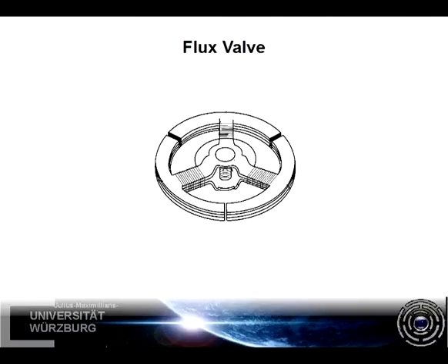The flux valve is essentially a compass that senses the magnetic field by exciting 3 coils using alternating current and measuring the resulting magnetic field. If there were no other field present, the resulting field would be cancelled out to 0, since the alternating current consistently causes alternating fields for very short periods of time. The interference from the Earth's magnetic field, however, causes a measurable difference in the resulting field, making it possible to deduce the actual horizontal component of the magnetic field of the Earth.